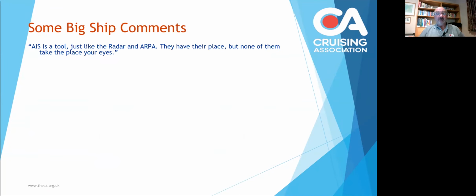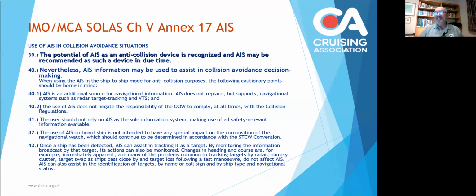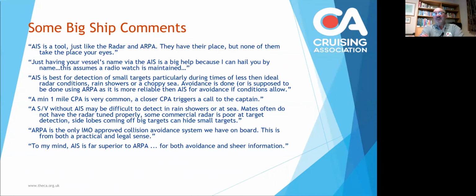There was, let me just go back a little bit, sorry. There was a discussion on a forum asking commercial seamen what they do in terms of AIS and collision avoidance against small ships. And some of these are very educational. So the first one: AIS is a tool, just like radar and ARPA. They have their place, but none of them take the place of your eyes. That's a very important lesson.